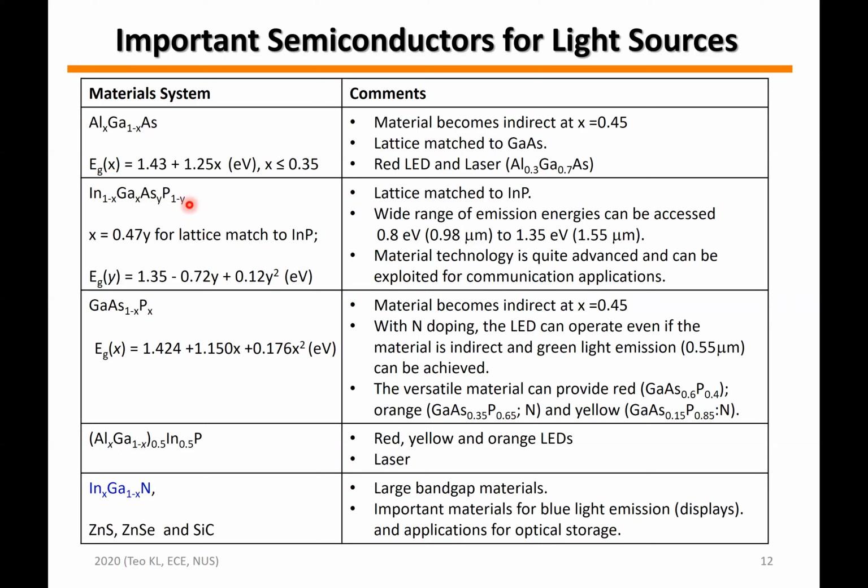Indium gallium arsenide phosphide quaternary alloy can be grown lattice matched to indium phosphide and is useful for communication application, especially in the 0.98 micron to 1.55 micron long haul communication.